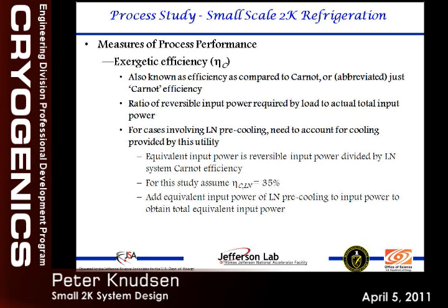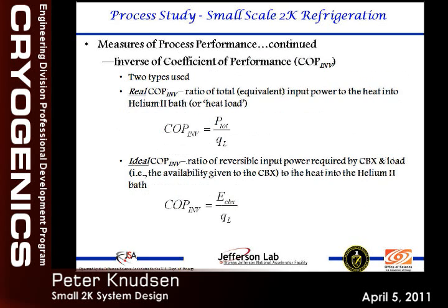And coefficient of performance, inverse coefficient of performance, we've talked about those two. In this study, we're going to use two different kinds of inverse coefficient of performance: one called the real COP inverse, and one called the ideal COP inverse. The real one is the actual input power divided by the load. So if this is the load we're talking about, 200 watts, and this is a megawatt, this would be 1 megawatt divided by 200 watts.